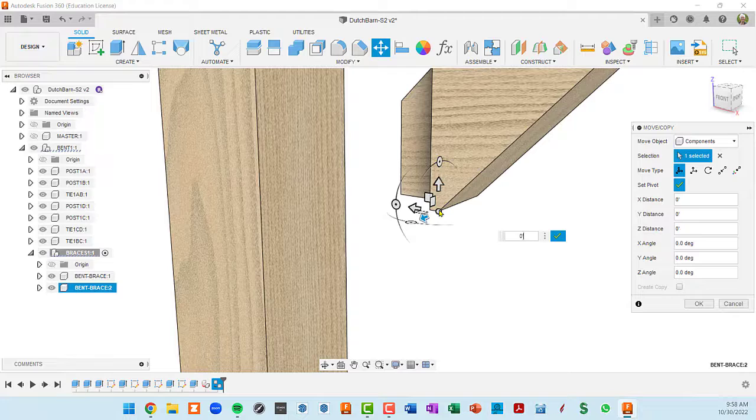Now here's the weird part. You're not done setting the pivot yet until you click this green check mark, which exists here and here, either one. They're both the same. I guess the rationale behind having to finalize this is you could actually move this and offset this wherever you want, and then finalize this. So this is something that burns me all the time. So I'll show you. I'm going to set my pivot to where I want it,